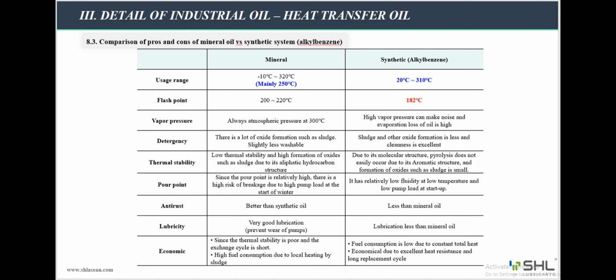Due to the composition of mineral oil, when continuously heated at high temperature, the carbon structure of the oil will fracture and form carbon deposits in the oil, causing system blockage. As for synthetic oils, due to the composition of alkyl benzene, the structure is more stable when subjected to high temperatures, so the possibility of deposit formation is much lower than mineral oil and it is easy to remove scale in the pipeline.